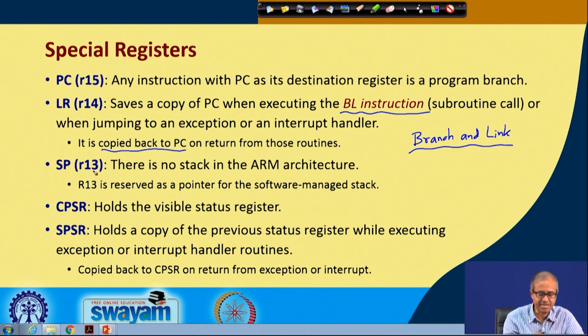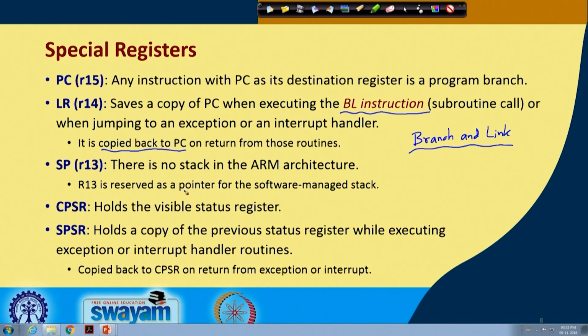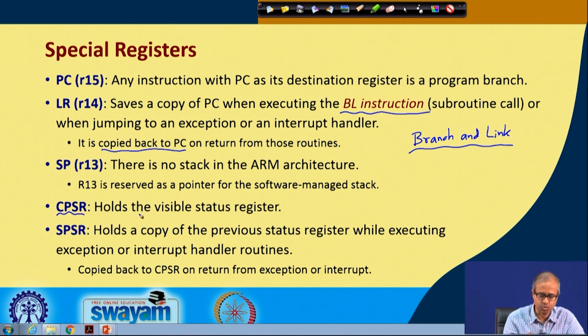So, you resume execution from where you left. And R13 is earmarked for the stack. Of course, there is no stack in ARM, I told you, but it is reserved as a pointer. If you want to implement it in software, you can do it. And CPSR, as I told you, holds the current status with respect to the program that is being executed, and whenever some exception or interrupt comes, the CPSR gets copied into one of the saved program status registers, SPSRs.